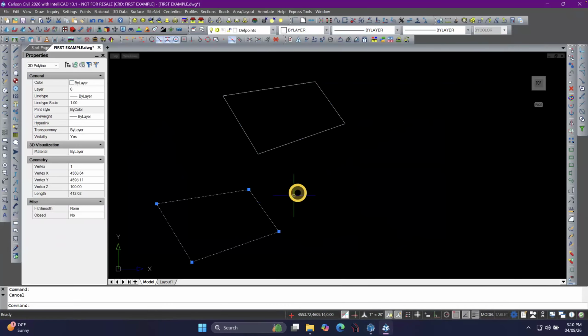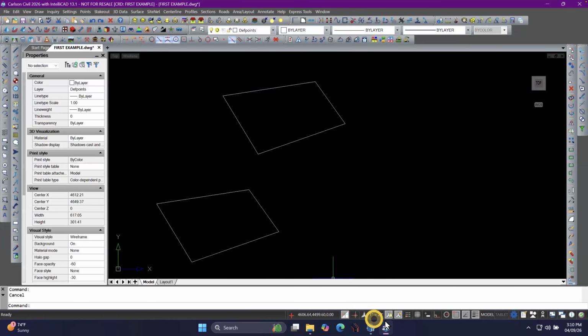You can also select a 3D polyline, and in the properties, it will show you all the vertices. And if you click in that field, you'll get a marker on the one that you can see. And this little arrow just steps you through it. And notice as you do that, the vertex Z value changes. Okay.